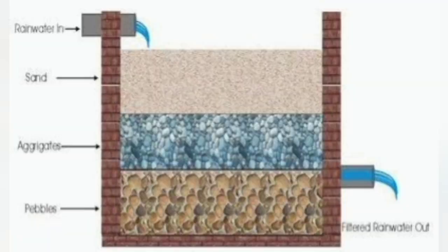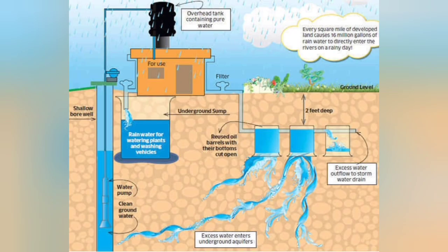The regional geological maps indicate the location of different geological strata, their geological age, sequence, boundaries, context of individual formations, and the structural expressions like strike, dip, fault, fold, flexures, intrusive bodies, etc. These maps also bring out correlation of topography and drainage to the geological context.